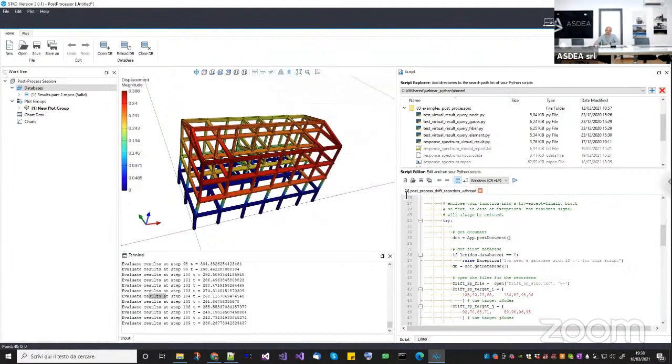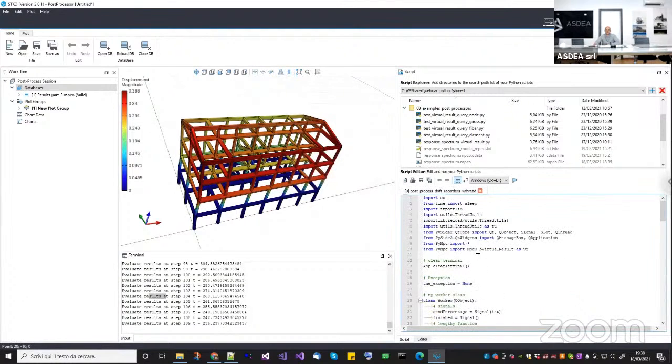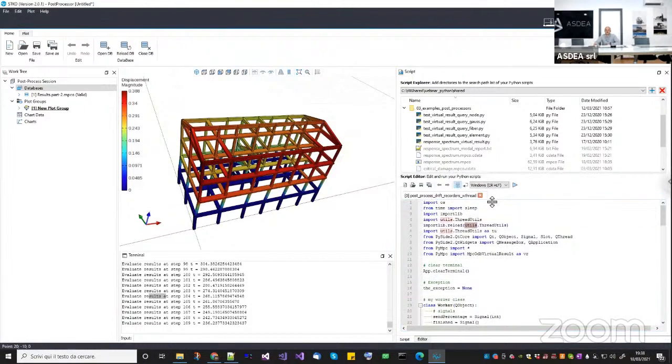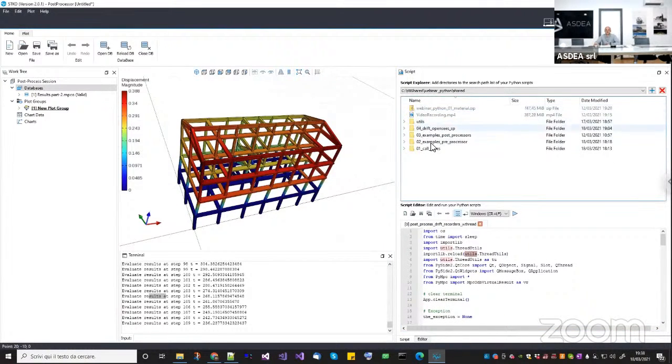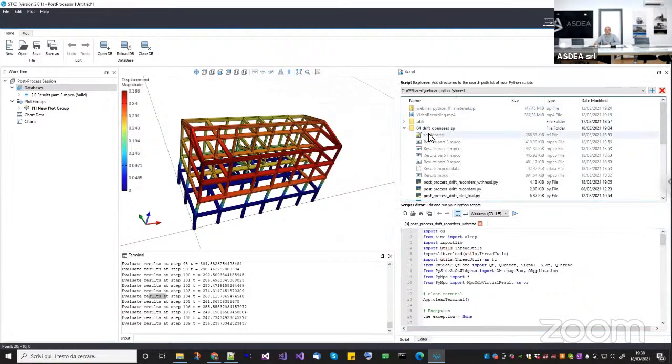Then coming to the same question, you said, yeah, but I'm trying, actually in this file here, I am using the utils file as a module. Now it works because the util file, even if this file is located here, I can access this file because this folder shared is stored inside the script explorer, STKO places this one into the Python search path. So when you call utils, STKO will find it because utils is inside this folder.